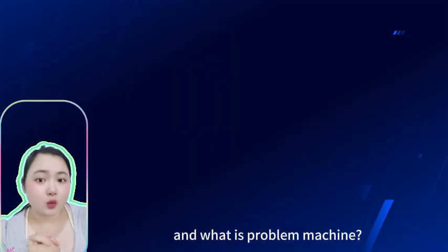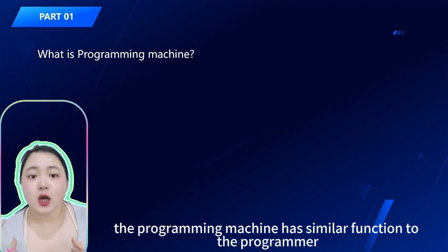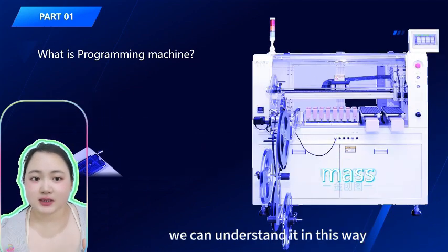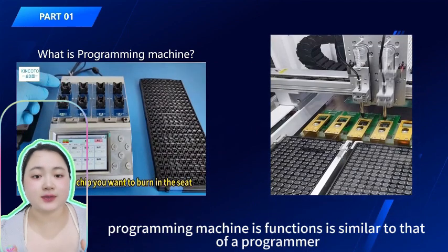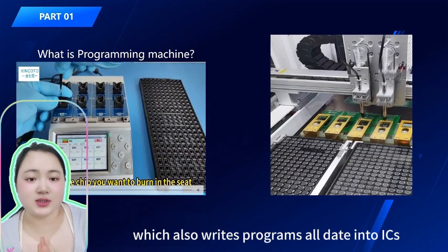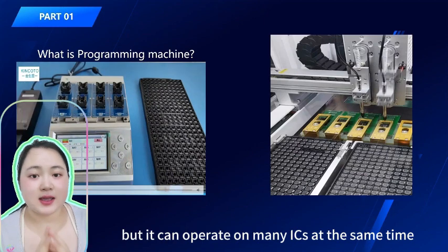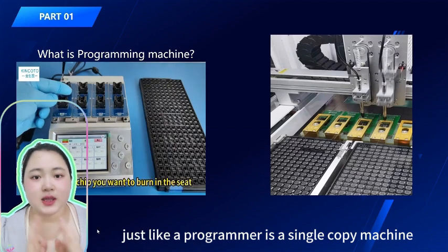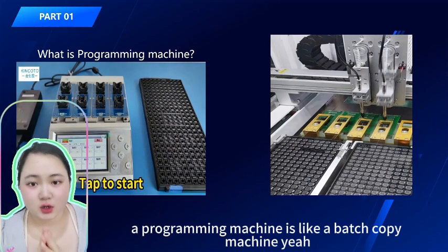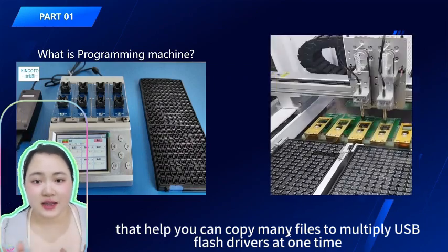And what is a programming machine? The programming machine has a similar function to the programmer, but it's mainly used in large-scale production. We can understand it this way. A programming machine's function is similar to that of a programmer, which also writes programs or data into ICs, but it can operate on many ICs at the same time. Just like a programmer is a single copy machine, a programming machine is like a batch copy machine that helps you copy many files to multiple USB flash drives at one time.